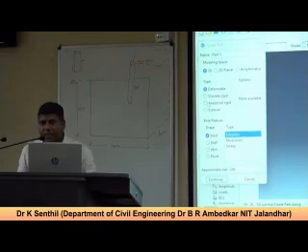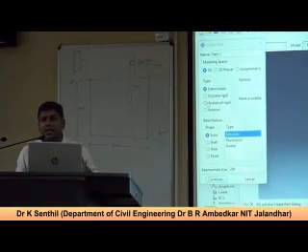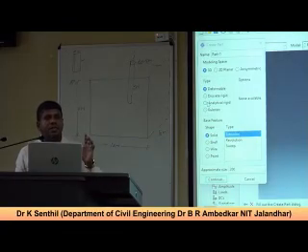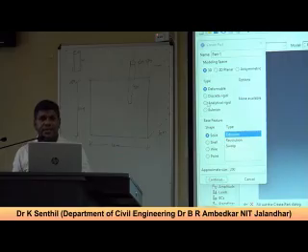The analytical rigid is purely rigid. No need to define any meshing. Nothing is required. No need to define the material properties. It works like a stone. Okay, if you look at a discrete rigid, you have to define the mesh size. You have to do it, but it will work as rigid.